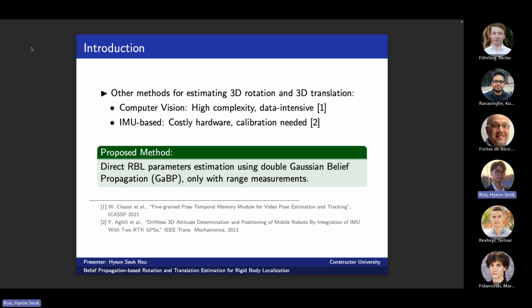And for each rigid body, you will have to have multiple IMUs because not only one will be robust enough to errors, and also each of these measurement units require high calibration, and this will be very inefficient, especially if you have a large number of these devices, for example, in Internet of Things or drone management and autonomous vehicles.